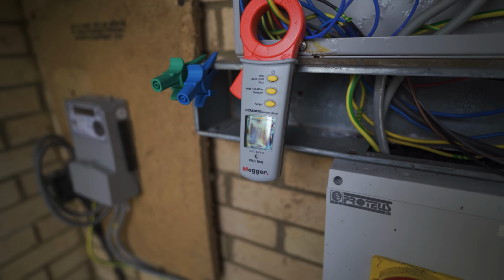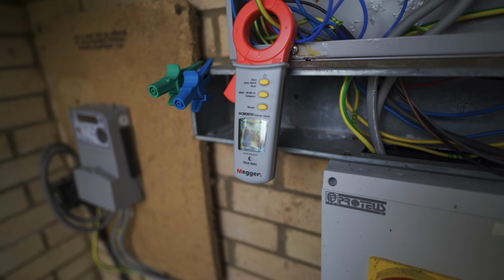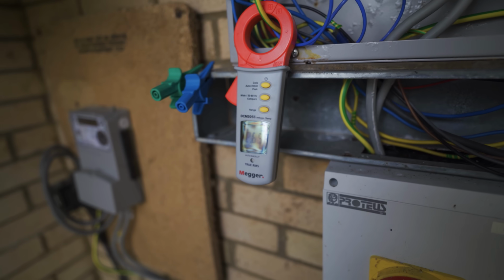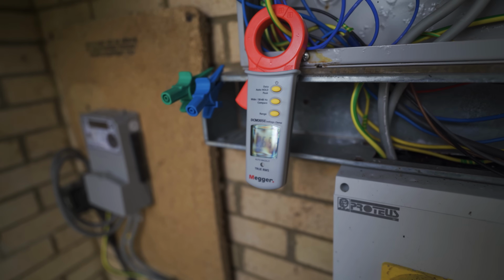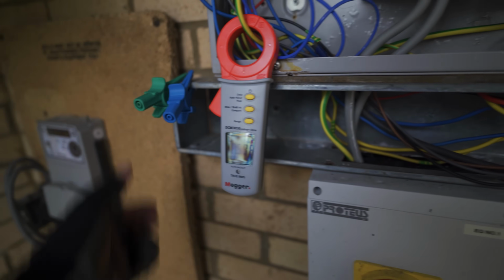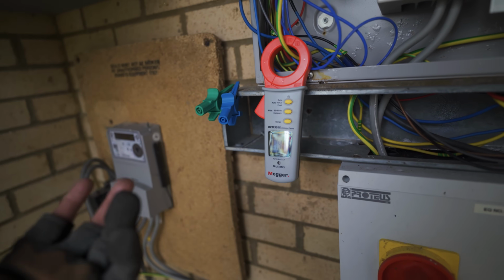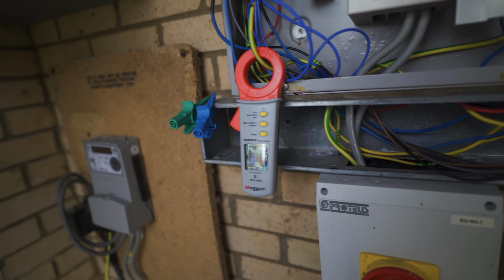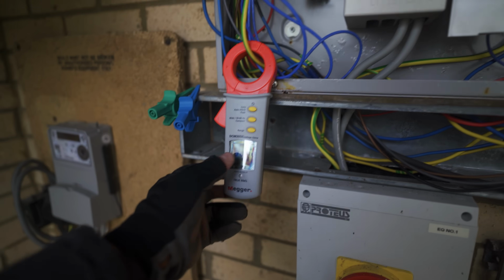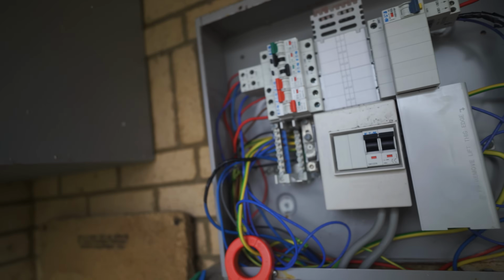Obviously, I ascertained that there was no live neutral fault. I cleared that by removing all the fuse holders, and then there was a dead short between live and earth and neutral and earth, but by removing all the fuse holders and taking everything apart and putting it back together again, that's now at 4 megaohms. That's actually really high. It's technically a pass, but that 4 megaohms on startup is allowing 30 milliamps of earth leakage through, which is obviously tripping the breaker.